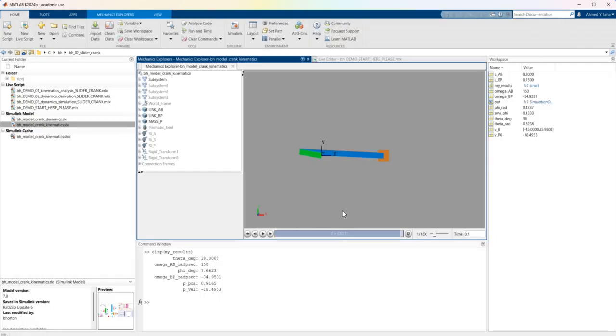That's for the first part, the kinematics. Again, I can play that as a video. If you would like to change the value for omega and make it going that way, just make omega a negative value, and this will change the direction of your rotation. These are the values that we got, so this will be okay. Now, let's go back to the original window we have here.